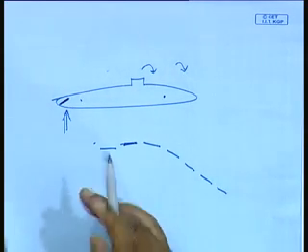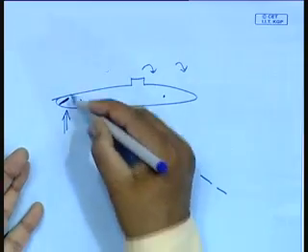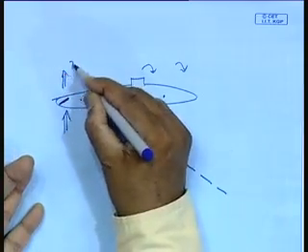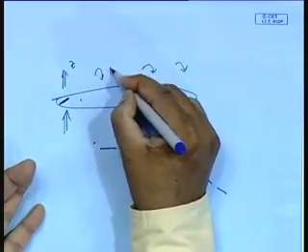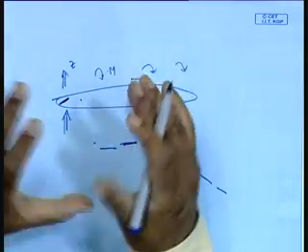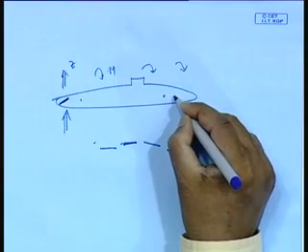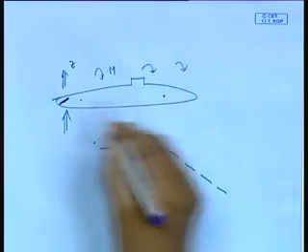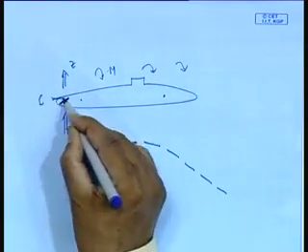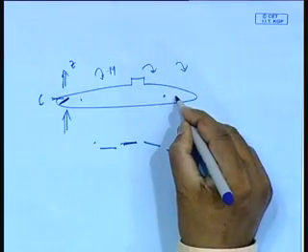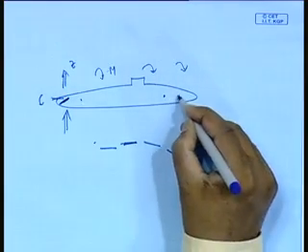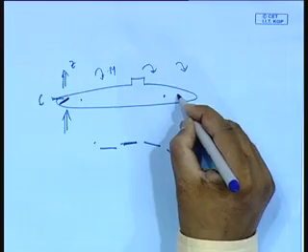So, the heave force created here is trying to push it up in Z, but the pitch moment is trying to nose it down. So, there is a reversal problem, opposite. But if you take a bow plane here, so for the bow plane, number one, I am bringing it this way. Now, supposing I want to come down, say my bow plane is here, somewhere here,